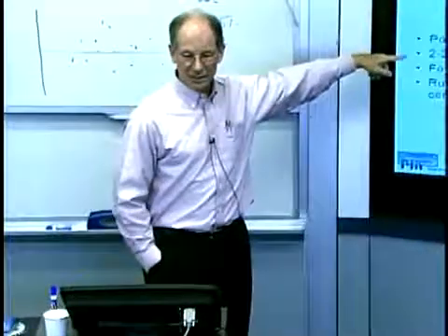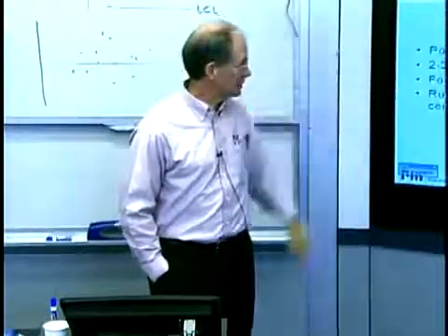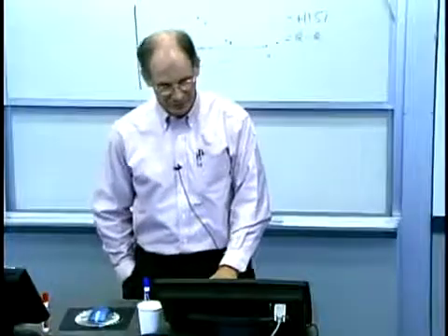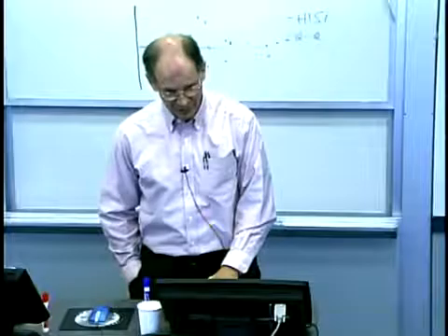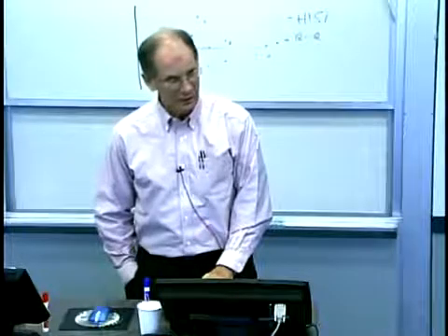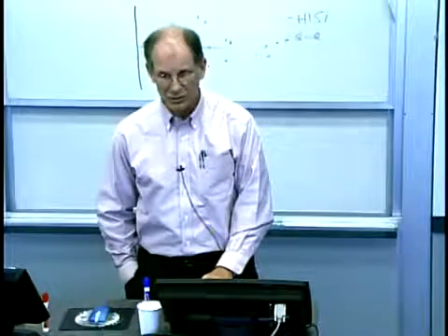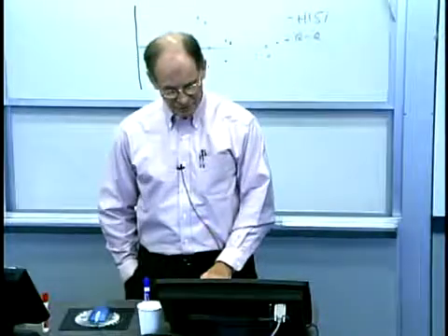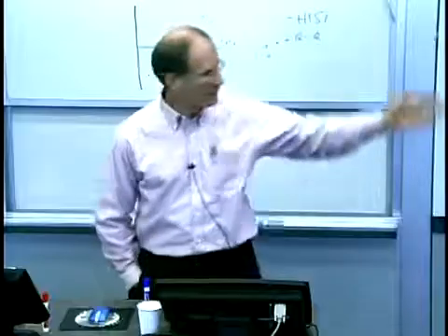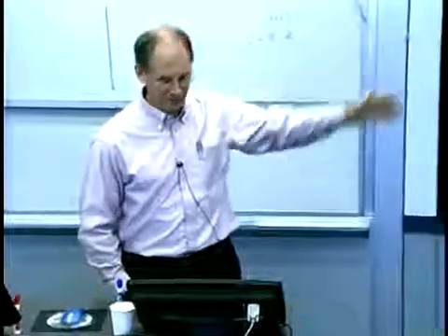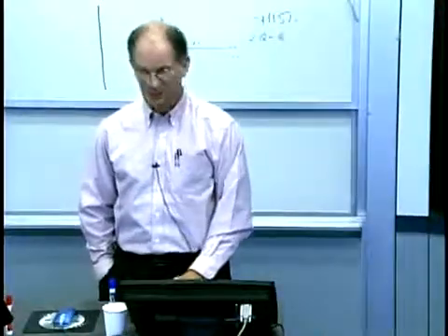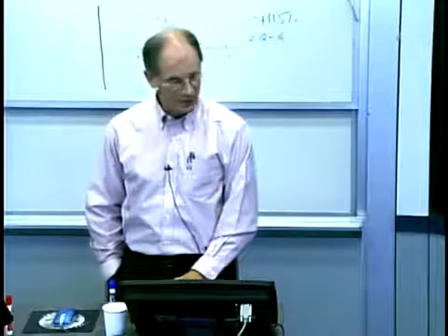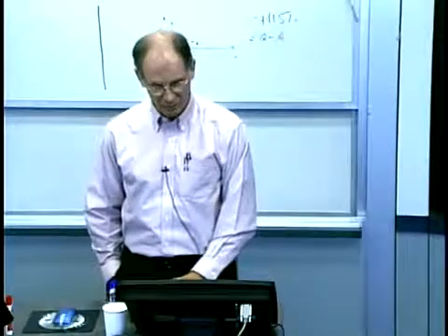These are the Western Electric rules that are in your text. Any points outside the limit, 2 to 3 points outside 2 sigma, and 5 points outside 1 sigma, that sort of thing. Okay, so just reviewing what we said, this is in control. Here's what the data should look like if it's in control, and if you see these types of behaviors in the data, it means something like this has happened: mean shift, trends, bimodal, whatever.